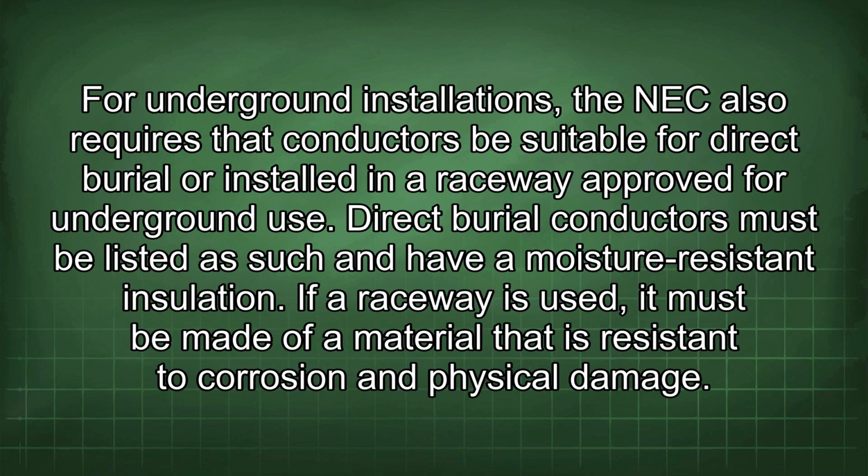For underground installations, the NEC also requires that conductors be suitable for direct burial or installed in a raceway approved for underground use. Direct burial conductors must be listed as such and have a moisture-resistant insulation. If a raceway is used, it must be made of a material that is resistant to corrosion and physical damage.